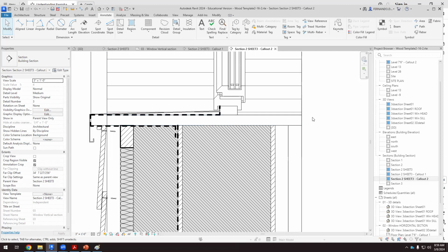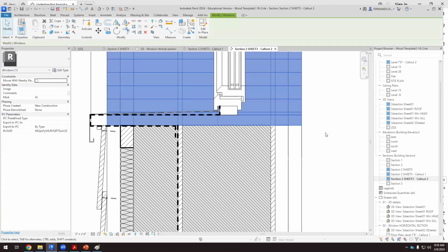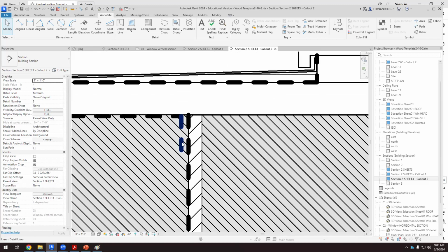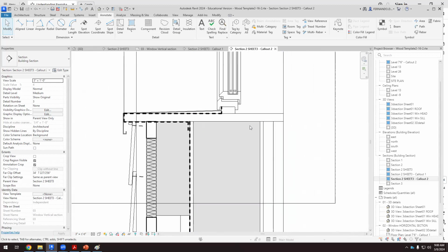So I did this solid element. I created this solid element as a frame. So I have to wrap all this element with this air tightness barrier, and I overlap the air tightness barrier that I have in the OSB board with this one. Okay, so that's why in this factory they were taping, or creating all those tapes, especially when we have the windows. So it's difficult, but that's the good detail. So I overlap the air tightness barrier.